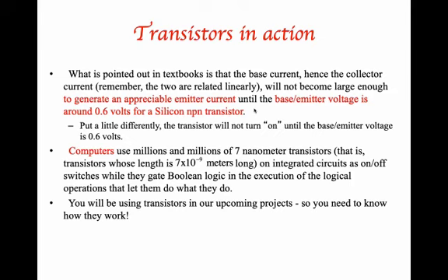What was happening in that solar robot was that there was a solar cell charging up a capacitor, and at a certain point, these transistors would turn on, and in doing so, they would allow the capacitor to dump its charge through the motor, and the motor would take off for some shorter period of time while the capacitor had charge.